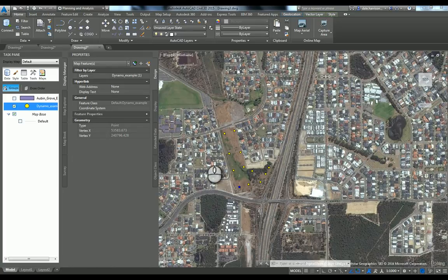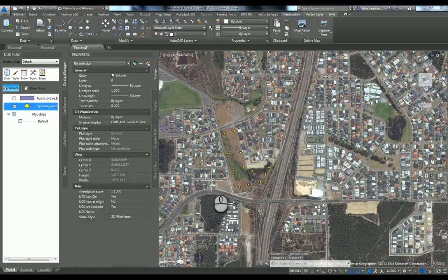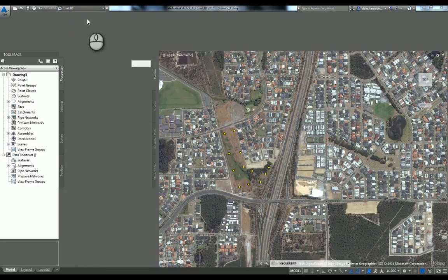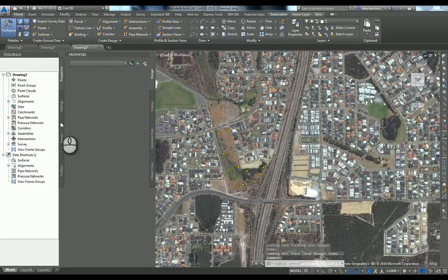So what I'm going to do is show you, using Dynamo, is take these points, use a matrix transformation and bring them back into Revit using a project base point. The project base point for this site I'm going to use is basically this point down here, which represents my base point. So using Civil 3D, I'll just toggle over using the profile switch.